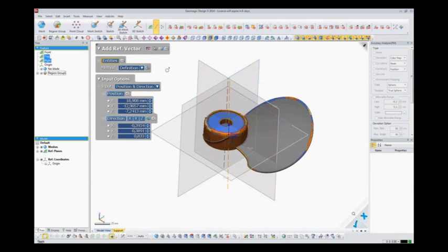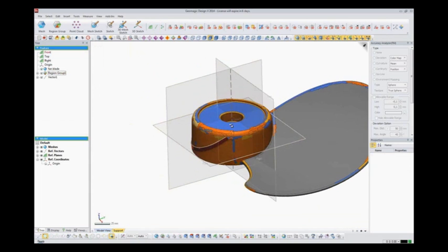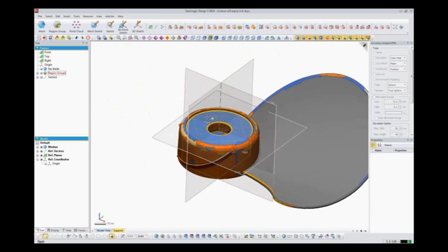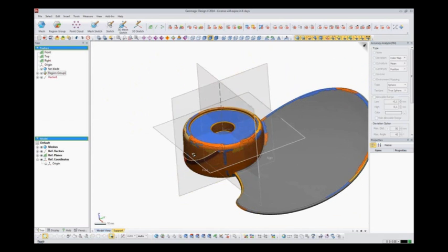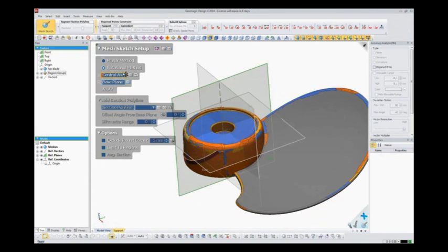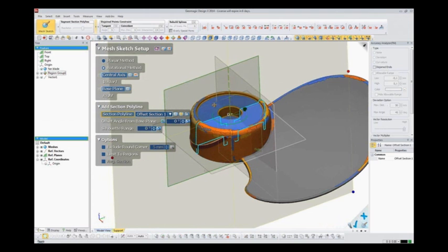So we will just make a revolving body. But it's possible later we can do some shape splitting and some drafting. So in this case, just do the revolving using a section through this hub, and then we need a circular section.